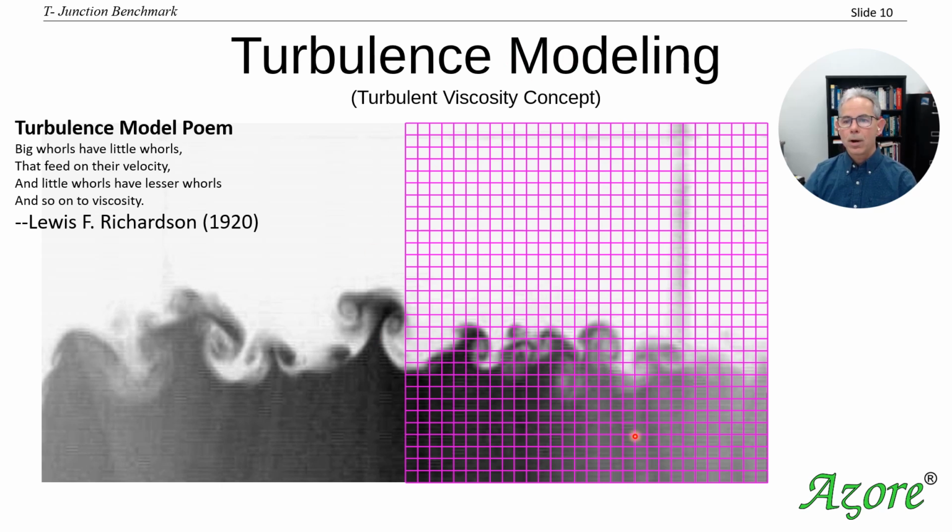And for our model, I've overlaid the mesh length scale that we're using for the benchmark that we're going to be simulating, because we're looking at a steady state representation of all of these whirls here. And you can even see at this mesh length scale, we are not capturing some of these whirls, they just pass right through. We wouldn't be able to capture this flow structure even with this mesh length scale. Perhaps we could make this mesh a little bit finer and capture the eddies shown here, but probably not the smaller eddies below this.